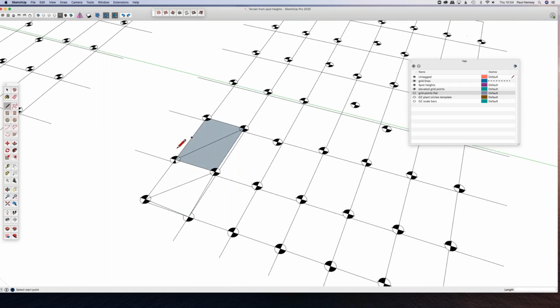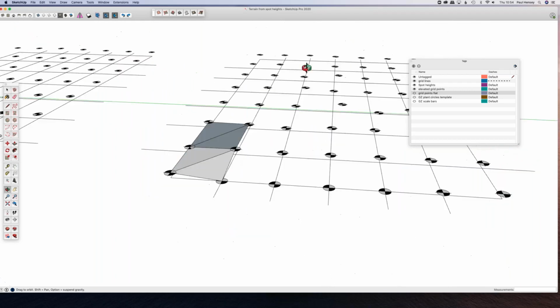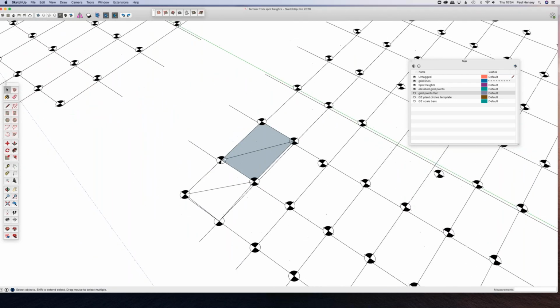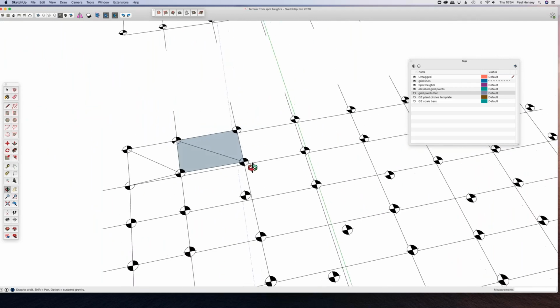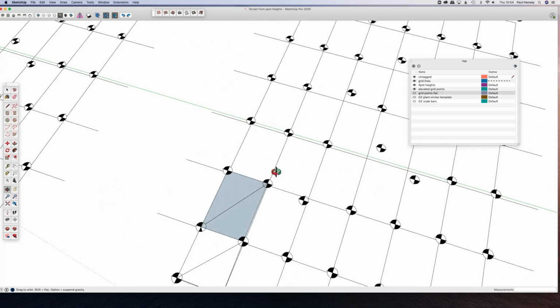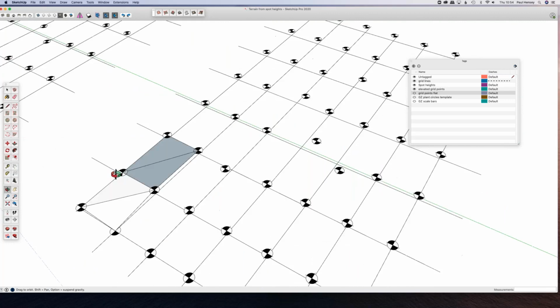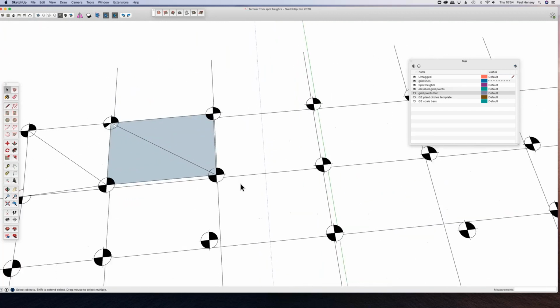A tip with doing this is make sure all your diagonals go in the same direction. Don't have this diagonal going left to right and this one coming from the top left down to the bottom right, because you will end up creating quite disjointed terrain. So it's very simple. What is really useful about this method is I'm just going to go down the center one here.